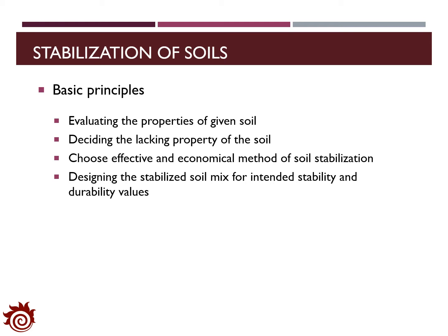After that, we want to choose the most effective and economical method for the soil stabilization. The cost of the materials and labor work should also be taken into consideration. Finally, we need to design the stabilized soil mix for intended stability and durability values.